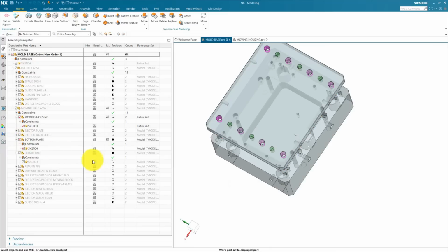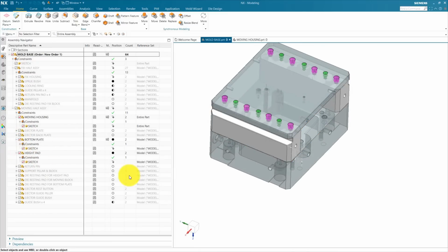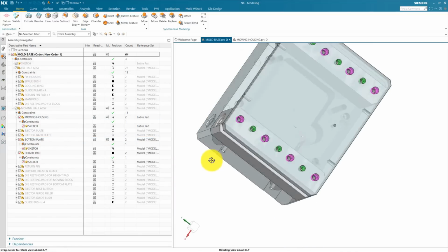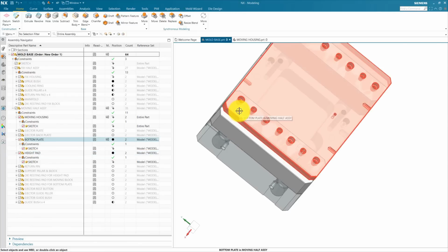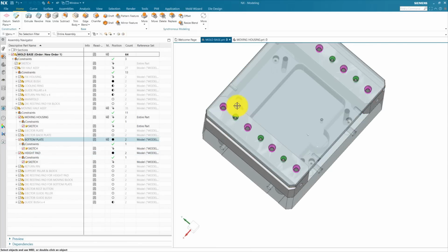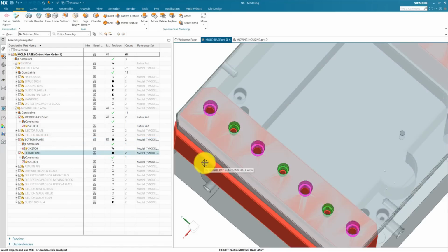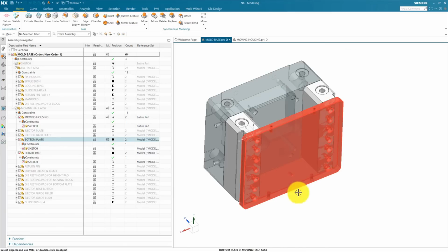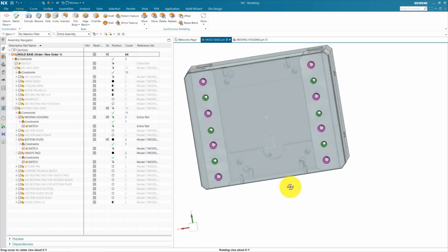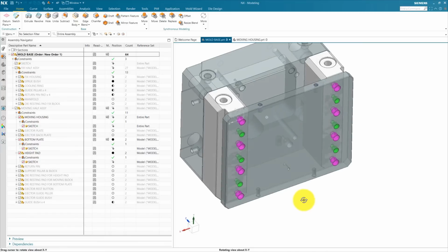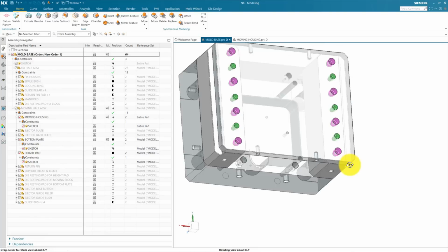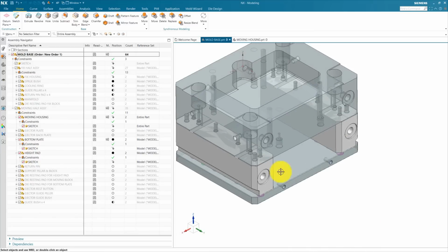So our bottom plate and height pad, we provided a threaded hole in our moving housing to bolt our height pad and our bottom plate together, and to bolt the bottom plate with our height pad we provided this M16 hole and thread. The bottom plate is not ready yet. We need to create a hole according to our tonnage for our bumper rod and ejector rod. So that operation we will do after completing our ejector assembly. In the next video we are working on our ejector assembly part.